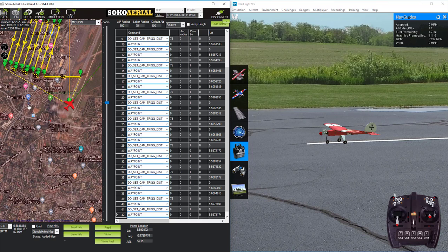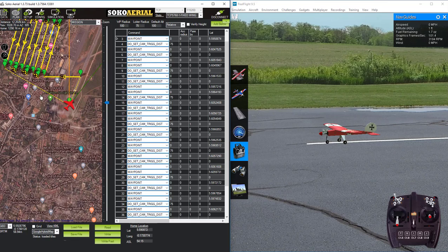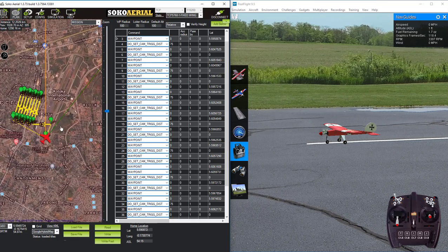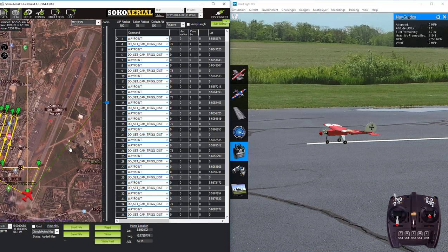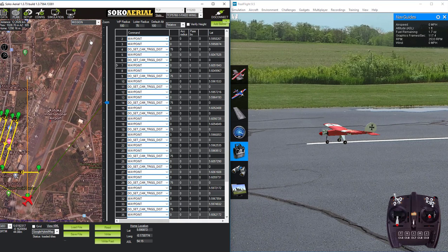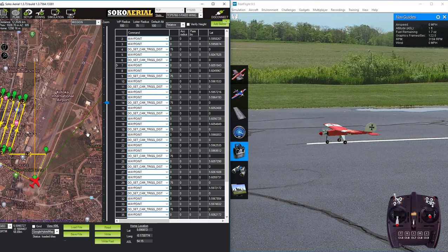Now, the interesting thing here is that I need to clear my polygon, sorry, and then plan for my approach in terms of how I want to land. And you could see that I cannot come this way and land like that. It's not a multi-copter, a quad system. The landing has to be a sequential system. So I'm going to assume, or I'm going to try and come from this side of the runway and then do a decent approach.